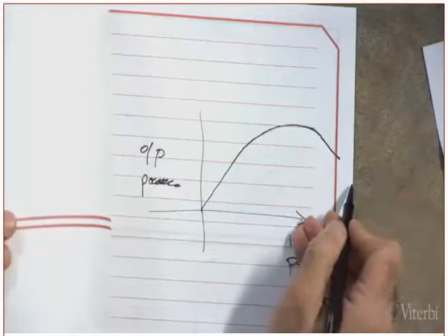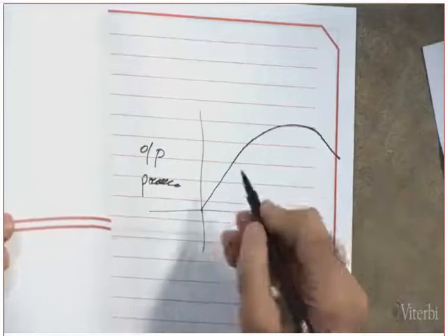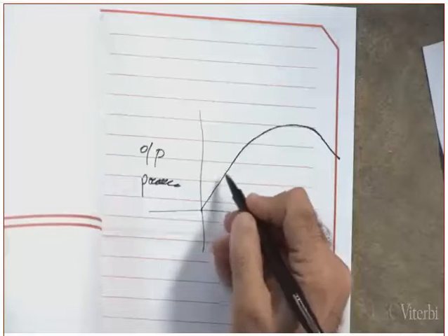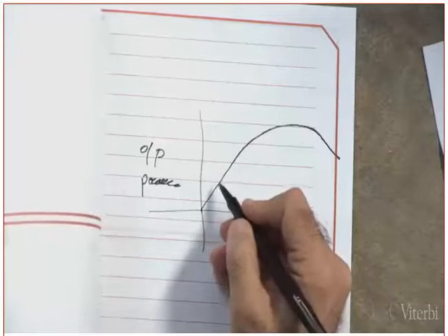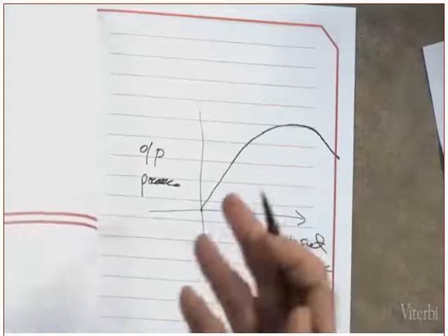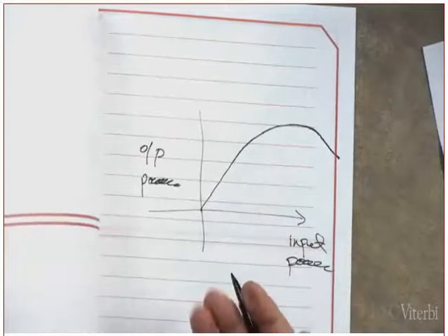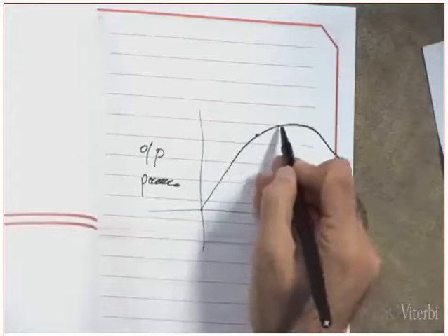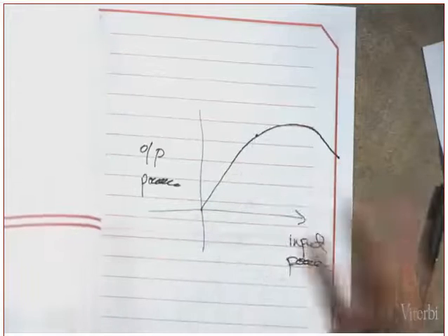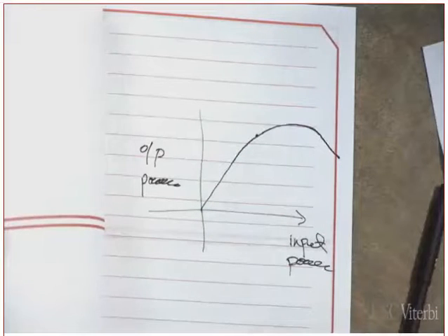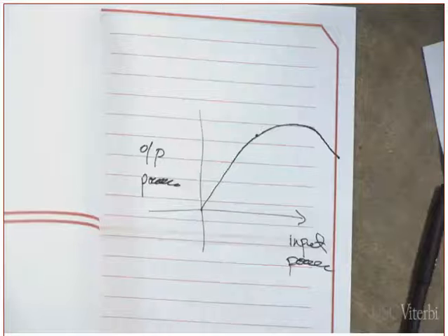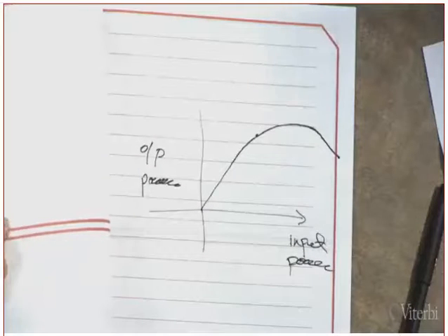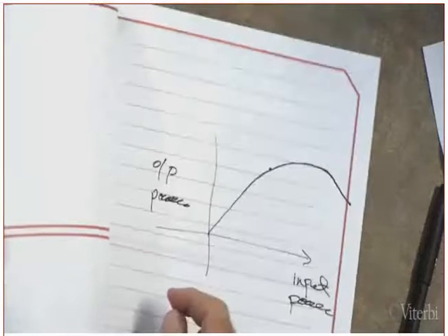I don't want to operate in the compression mode. Clear? But I also don't want to operate in here, because in here the efficiency of the amplifier becomes lower. I want to operate the amplifier closest to the maximum efficiency, so I would like to operate it here, somewhere in here. Now keep in mind, once you get non-linearity, all the side spectrum, all the side lobes that you get rid of using filtering will come again, will regrow again, if you do have non-linearity.